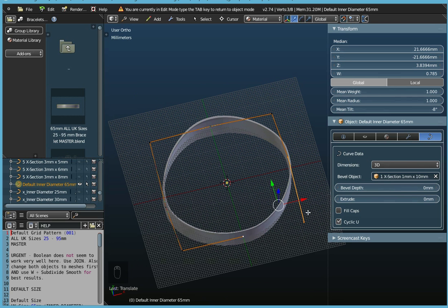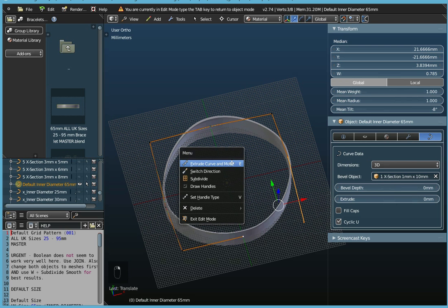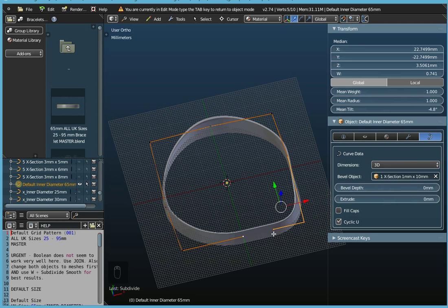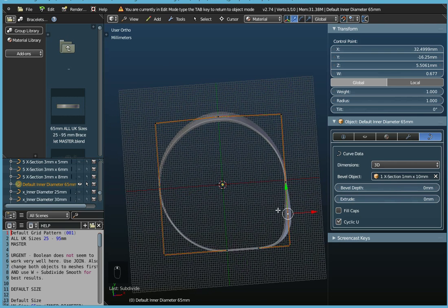will take these 2 control points and it will subdivide them and put another control point in the middle. And it will take these 2 control points and put another control point in the middle. So if I do that, you see the control points appear there and there. What I get is a more square format in the corner here. So instead of being round, when you've just got 1 control point here, you get a round object. Bracelet, a round bracelet I should say. If we actually introduce control points here, we can create a more square bracelet.